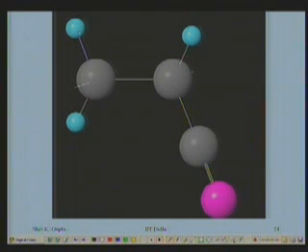These side groups R1, R2, R3 are hydrogen. The fourth one is CN. This is nitrogen, this is carbon. This is polyacrylonitrile, which substitutes for wool and is used as a starting material for making carbon fibers. We have to slowly remove this nitrogen and hydrogen and make it a chain of carbon. Ultimately, in three dimensions, it will form the sp2 bonds of carbon and form a fiber.